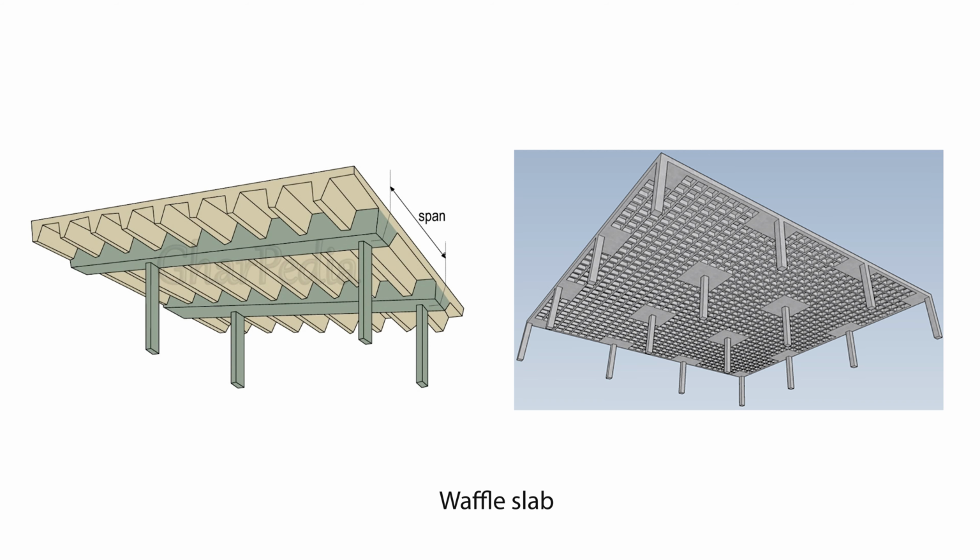For the T slab, it is generally used because in cast-in-place there is a waffle slab kind of structure, where the waffle helps the slab have intermediate beams. Those beams help the load transfer uniformly to the main beam, and that is the main aspect of the secondary beams, to transfer the load uniformly. So that's the main thing which differs between the two.